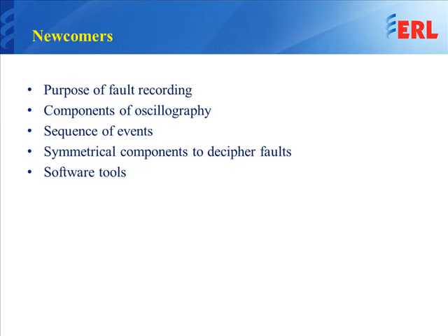So for new people getting into this kind of field, the purpose of fault recording needs to be known. Also, the components of the oscillography have to be understood, and then we'll recommend knowing the sequence of events, what that is. And using symmetrical components to decipher faults is very critical, since microprocessor relays and digital fault recorders offer these capabilities. And at the end, of course, using what the software tools give you is really important.